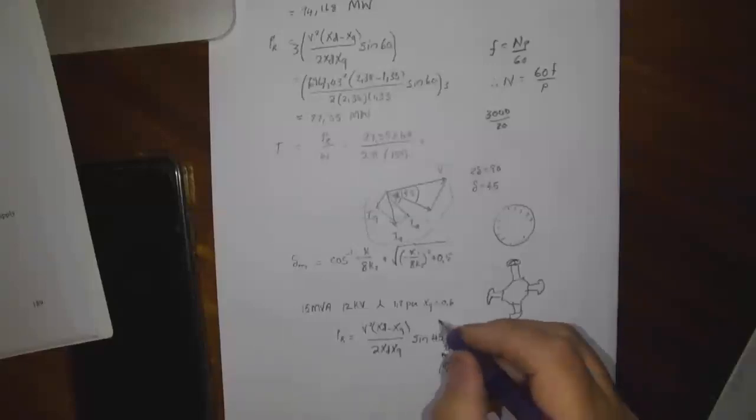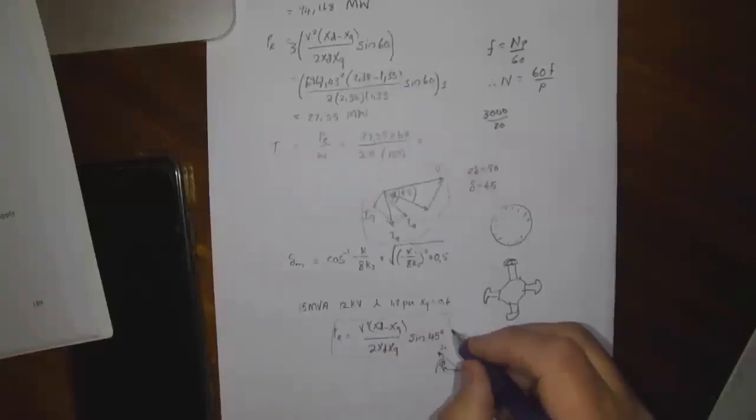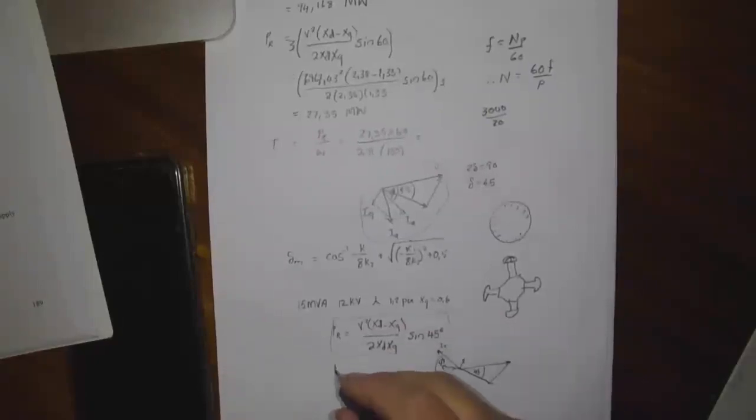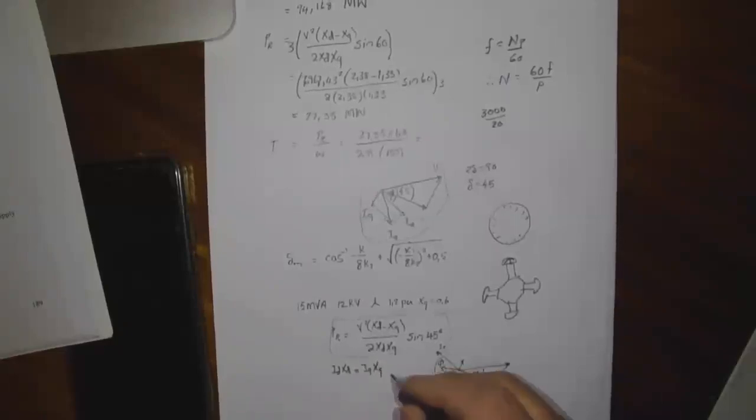So basically, sir, after I've calculated my power, because I'm asked to calculate the armature current, can I just use the formula S over root 3 multiplied by my V terminal? No, it's only because you've got the reluctance power. So for this current, you're going to say that ID XD is equal to IQ XQ is equal to cos of 45, which is 0.7071.